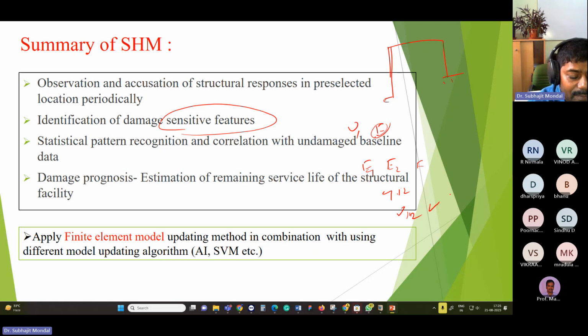If you measure the natural frequency, you'll observe that not all the parameters are sensitive enough to the natural frequency of the motions. So you need to extract sensitive features. Otherwise, whether you use SVM, ANN, or any other method, no method is going to give you a satisfactory result, because the data itself is not sensitive enough.